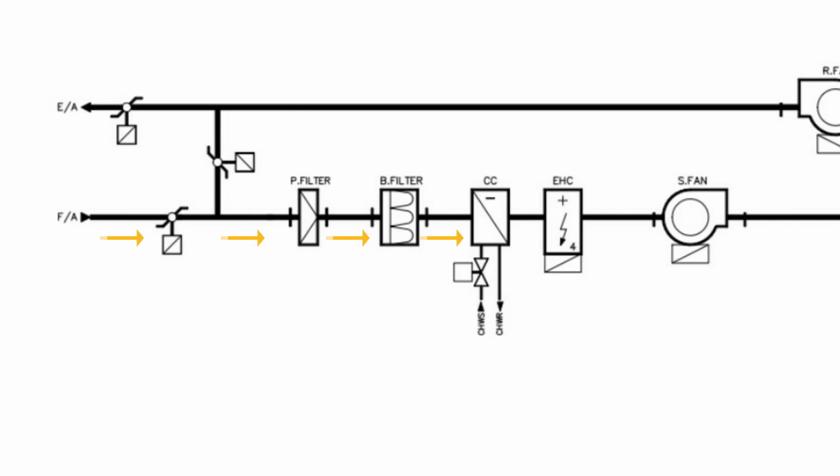The direction of the air is one factor to consider when installing a sensor. Our task is to monitor the filter status. Analyzing its function, it deals with two air pressures, before and after the filter. So a differential pressure switch is what we need in this situation. The differential pressure switch will activate and send a signal to the controller if the pressure after the filter drops. That is an indication that the filter is blocked or dirty.